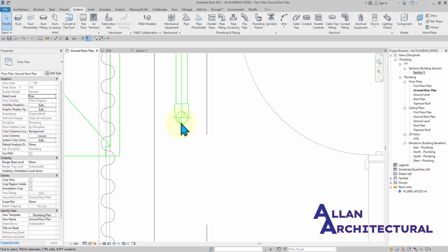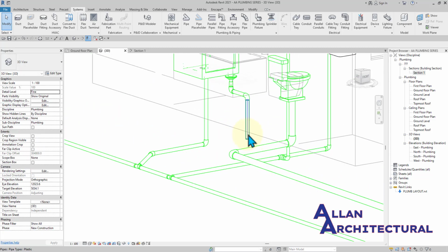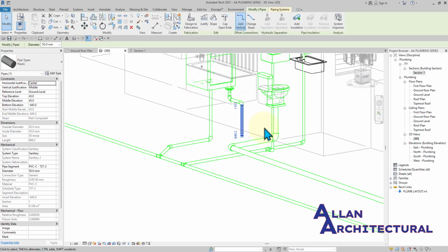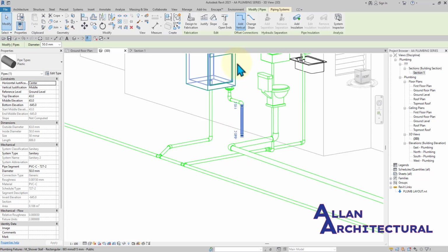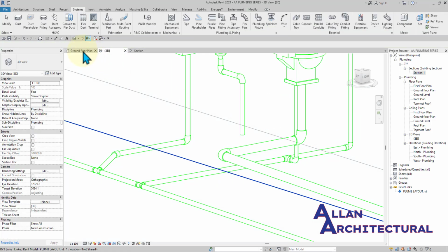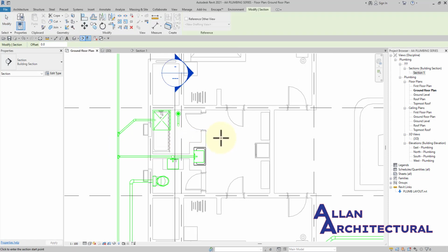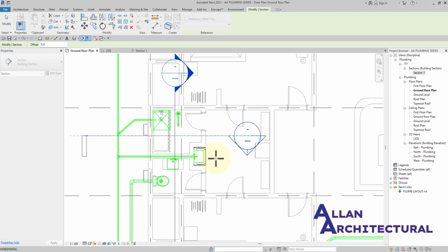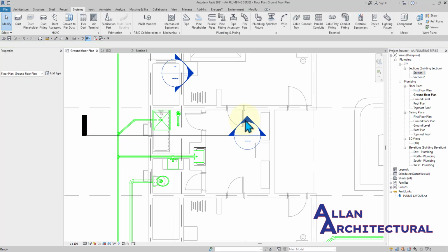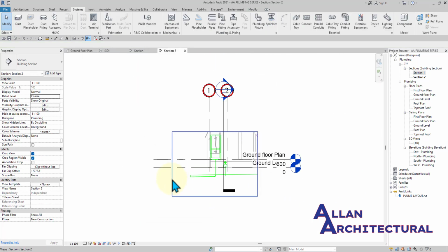So that's the elbow, and just select that, hit the Tab key. Let me get into the 3D view, and I'm going to want to create a section also somewhere around there. All right, so just CS on your keyboard, and then we're going to create that. Let me first create that section in there, somewhere around here, and I'm going to change that view. This is perfect. Just double click in there, and we have this in here.